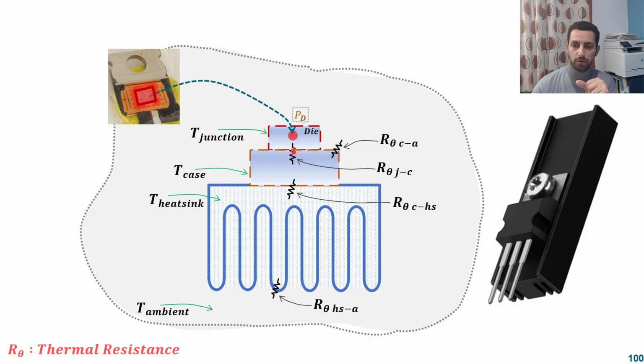The heat will come here, and will find two ways, the way to the ambient and the way to the heatsink. And because we have done here a good thermal contact with very low resistance, it will prefer to go to the heatsink and be dissipated by the heatsink, okay? And the amount of heat dissipated directly by the case will be very tiny. And we will see this actually from the data sheet, where they specify this one is much, much higher than these two.